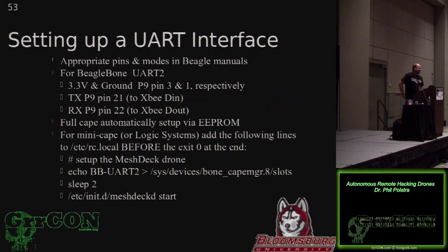If you have a mini cape or a Logic Systems cape, you're going to have to tell it, hey, by the way, use these pins, please. And here's how you do that. You have to, as root, echo BB-UART2 to this file location.